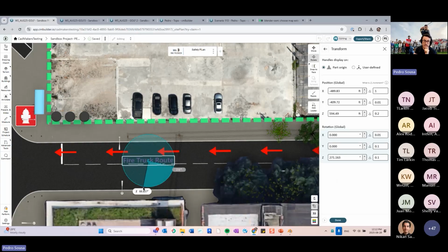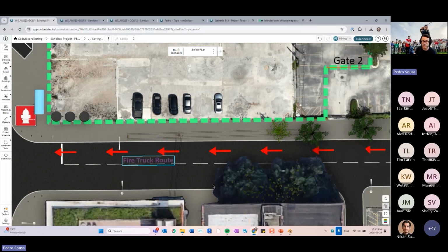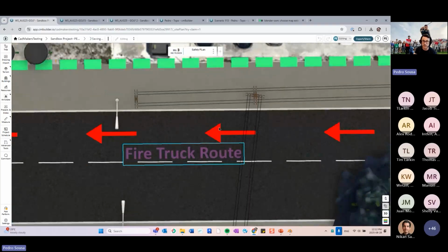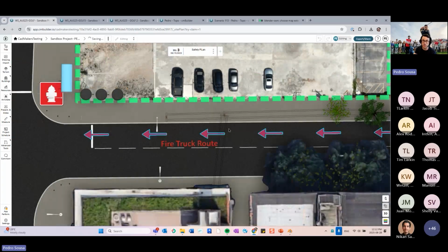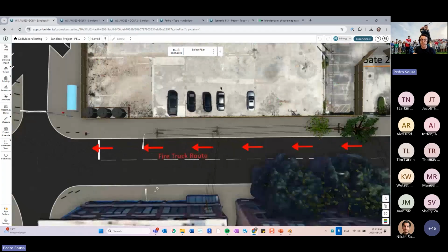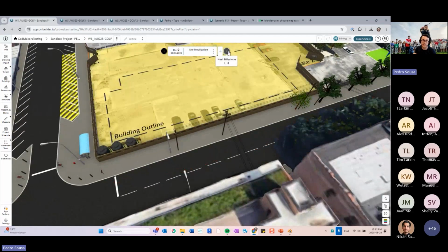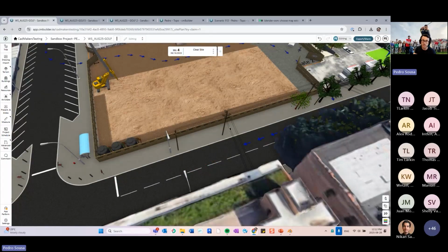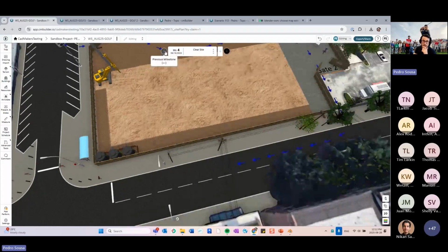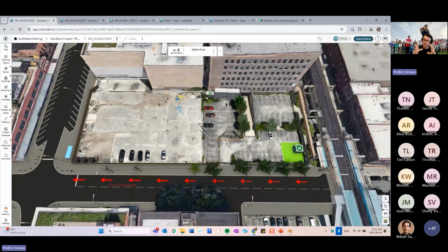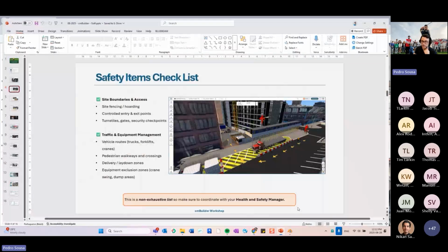And if you want these elements to show only in one milestone, of course, you're going to put the start and the end date at the same milestone. So I want the beginning and the end of this resource to show only at this milestone. So now if I go back, those objects are not there. And if I go past that milestone, those objects are also not there. Okay, so this is a very good way to contain all of these visuals for your site safety plan in one single view.